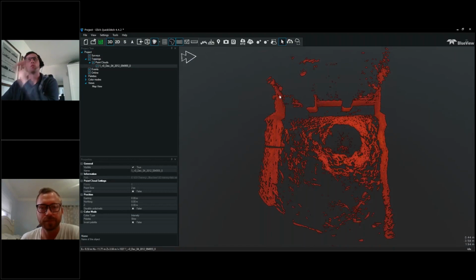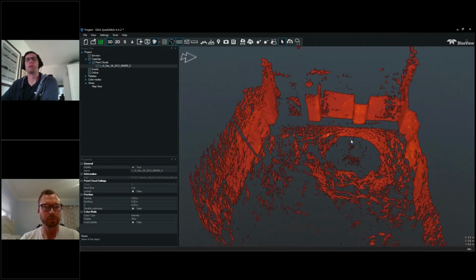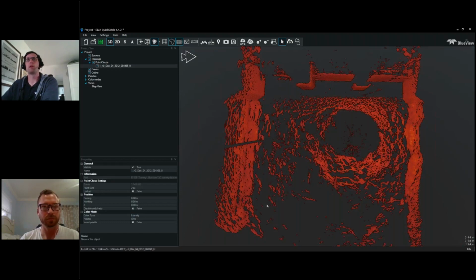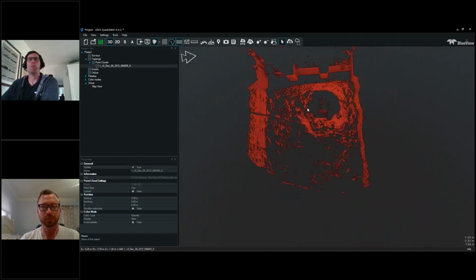Yeah, so here's one data set. So this is one scan location, one point cloud. We can see kind of the trademark donut hole or blind spot where the tripod was actually located. And we can see the surrounding area. So right off the bat, we can see it's an area with 3 kind of close walls and then no back wall here.